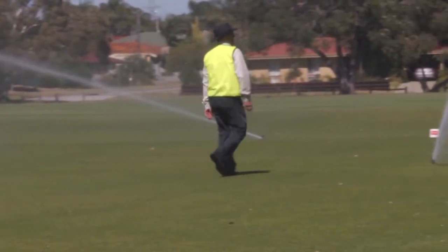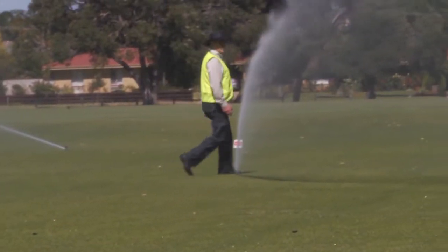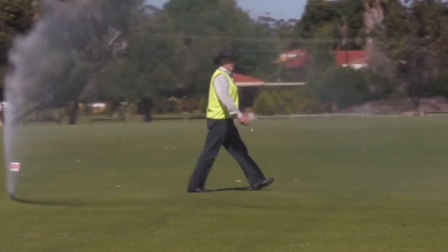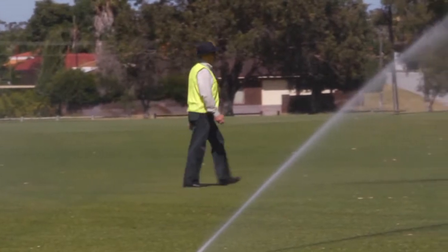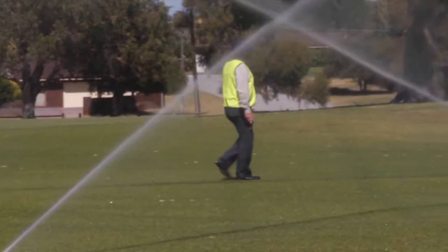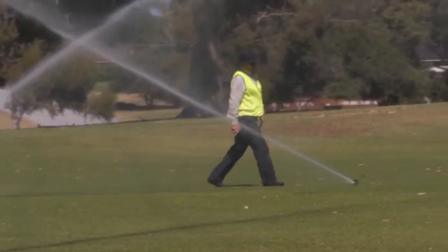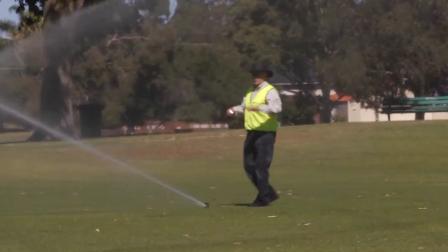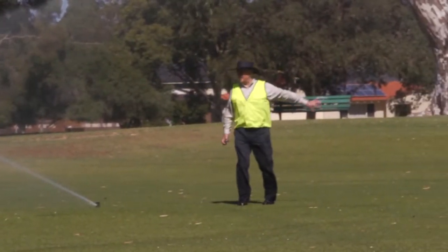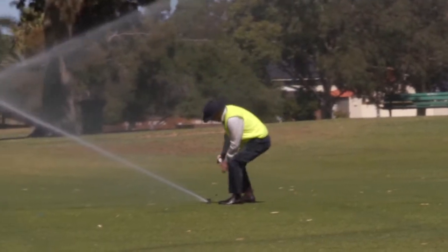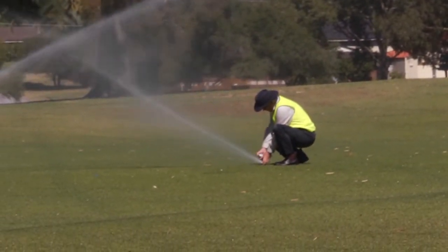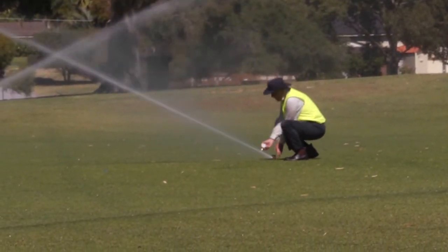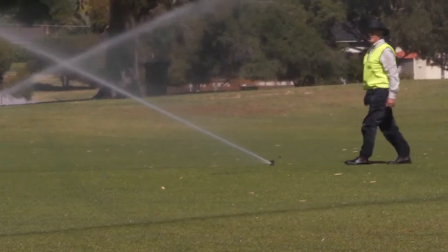On this particular station, there are actually two valves operating on this station, and I know from looking at the drawing before we started the test, there's a ring main going around the area and the solenoid valve controlling this group of sprinklers is located at this end. So by checking the pressure on this sprinkler, that's 410 kPa.